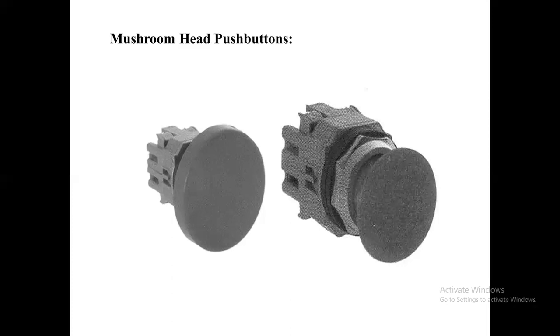The switch on the right side of the figure is a detent push button. That is, when pressed, it remains in, and to return to its original position, it must be pulled out. It is called an emergency stop button or e-stop switch.